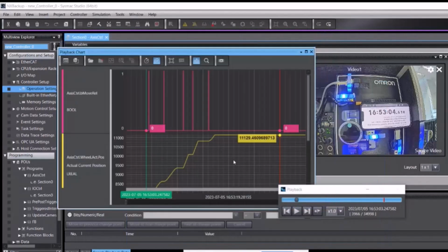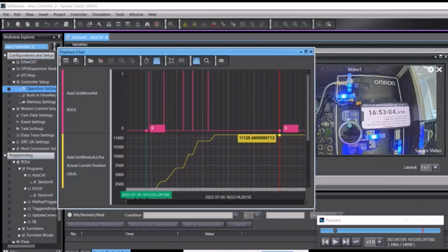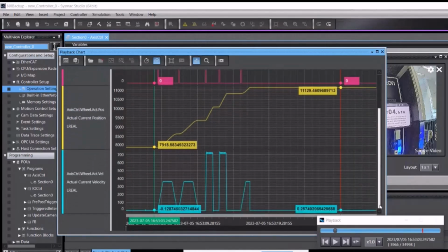So now you will see a review of exactly what happened on the machine with the servo, if I can size the window. So let me scroll down here. If we look at the move here, we can see a nice acceleration, deceleration, acceleration, deceleration profile. But now we can see the abrupt stop that was reported by the maintenance engineer, where we've accelerated our servo, travel at a constant speed, and immediately stop.